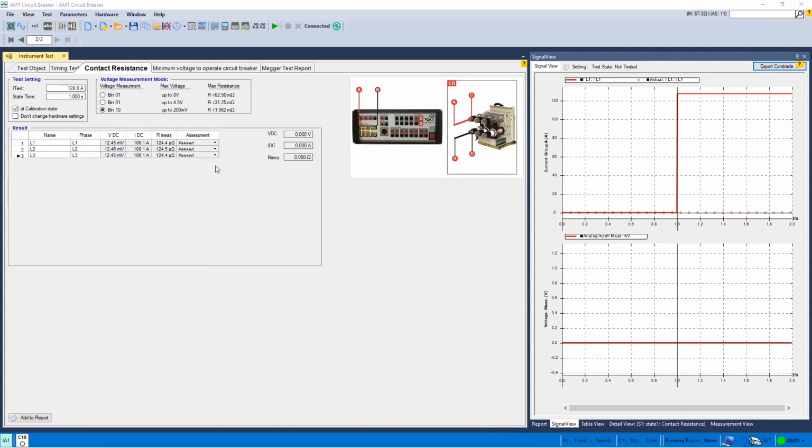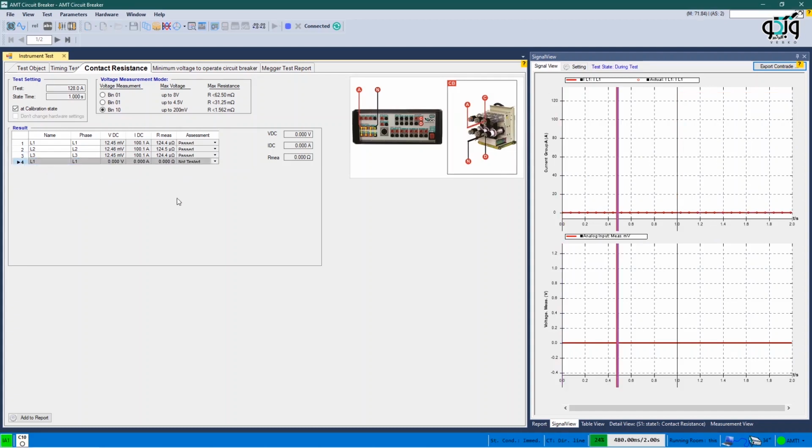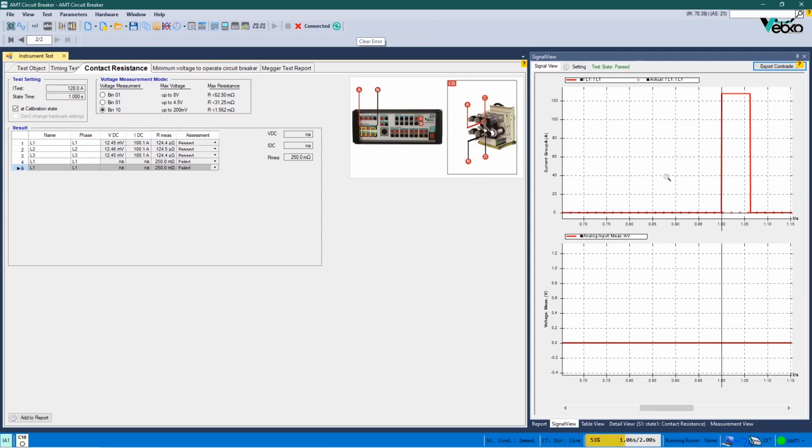In performing this test, it is imperative to note the following. First, Error Other in performing the test means that there is a problem in connections or the current route resistance is too high so that the device is not able to provide the burden needed to inject the current. Therefore, in this case, check the actual current from Signal View. If the current is injected, but the difference with the specified current is too large, in the cases where the route resistance is high, the test current must be decreased, and if the actual current equals 0, the connections must be examined. Make sure the CB is closed.